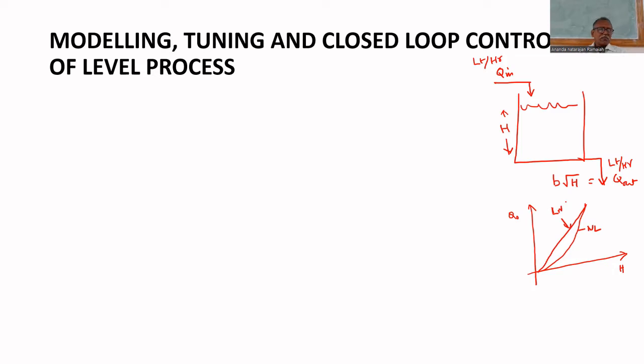What you studied is a linear control system, not a nonlinear control system. Here, we have to apply this linear control theory to control the level of this process. That subject is called process control. So most of the controllers that we use are linear controllers on a nonlinear system. A PID controller is a linear controller.